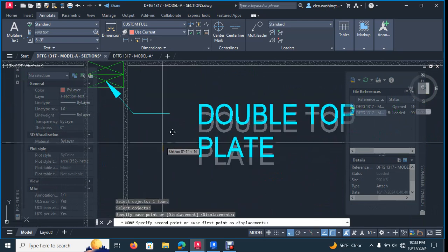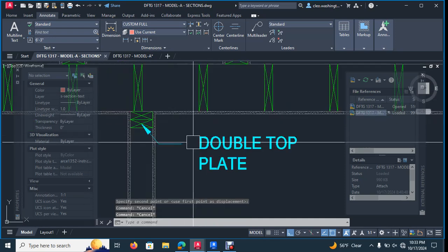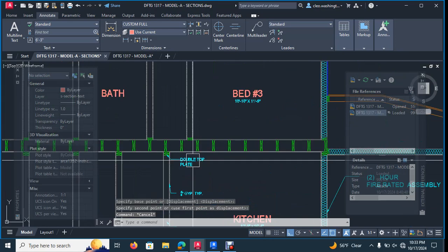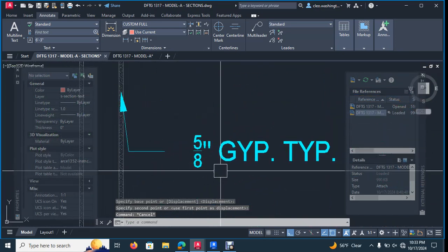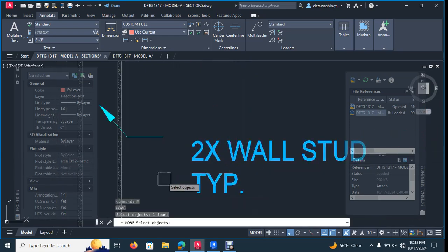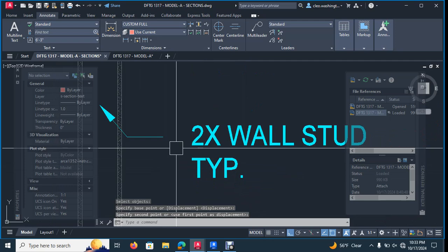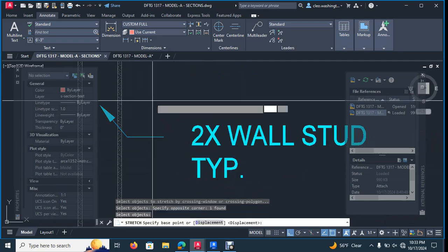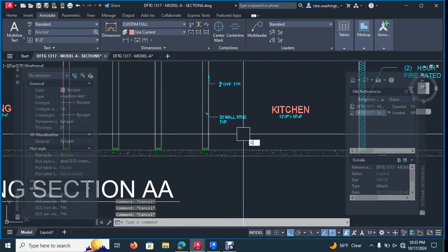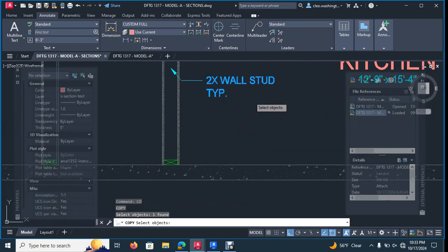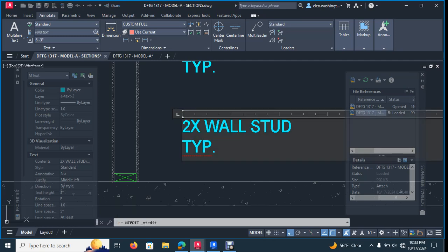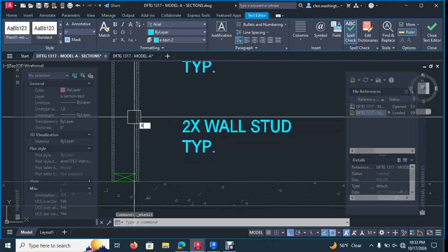So make sure that your text is aligned with the leaders. You can stretch that just like we stretch everything else. Move this up because it's not aligned. And let's go ahead and stretch this just a little bit. Just hit S and pull it over. And then let's go ahead and copy this. You're going to call this bottom plate, BOT.